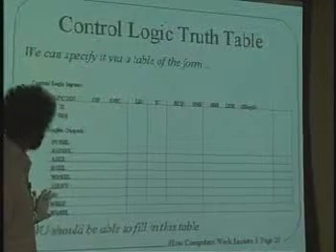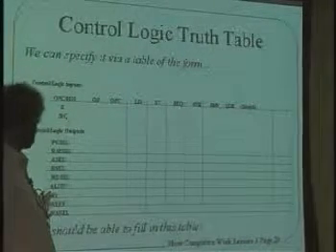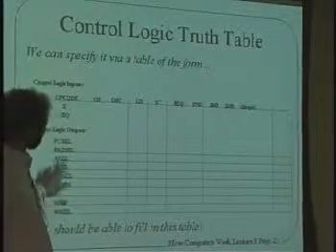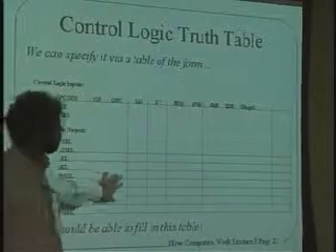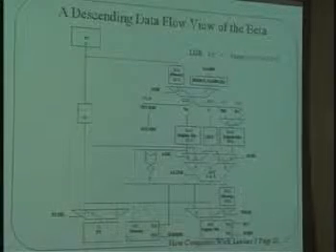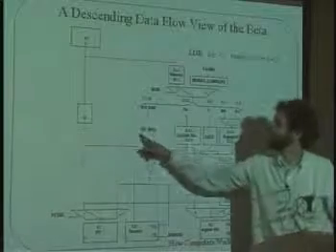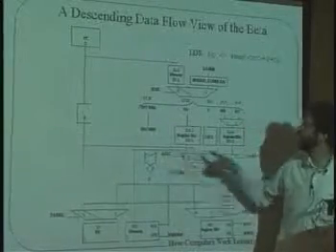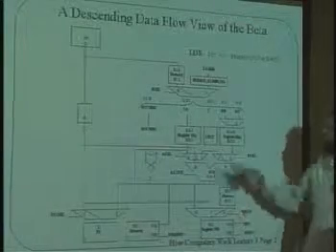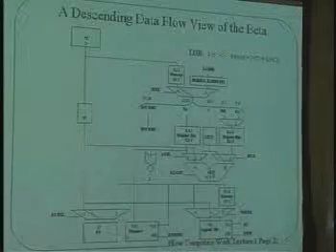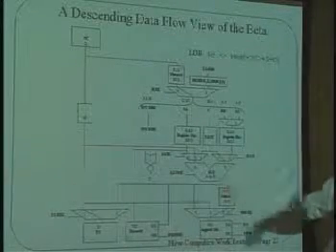And then the write enables that go to the 3 files down at the bottom will also depend on what we're trying to do. In all of those cases, you can fill in a table here that fundamentally is taking, in this picture, an indication of what is the opcode, what is Z, and depending on those things, what should each one of the other control inputs to the selectors and to the E inputs down here be, whether they should be on or off, what path they should choose.